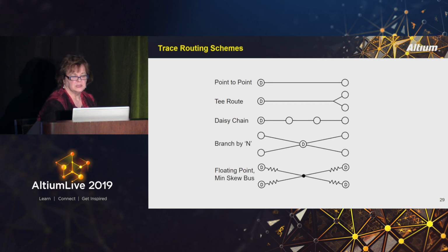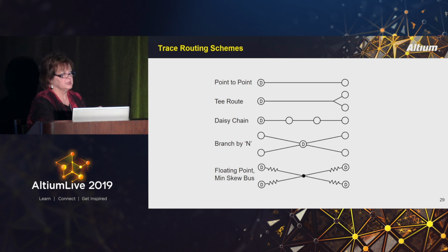Some trace routing schemes. Rick showed this particular slide in his presentation if you were here. I'm going to take it a few steps further. So if you weren't in Rick's class earlier this week, what he's showing here is a point-to-point. You have a single signal and it has a driver and a load, and you route from one to the other. If you have multiple routes that are drivers or loads, then you would use a T-routing situation, and you'll see more about that in just a second.